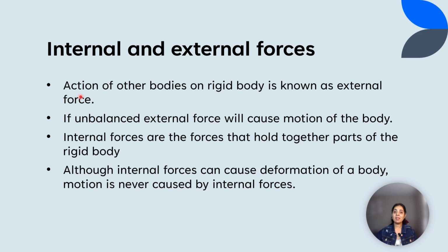Internal and external forces. So what is an external force? It is an action of other bodies on a rigid body, and is known as an external force. And if that external force is unbalanced, then it will cause motion. Internal forces are the forces that hold together parts of the rigid body. Although internal forces can cause deformation of a body, motion is never caused by internal forces.